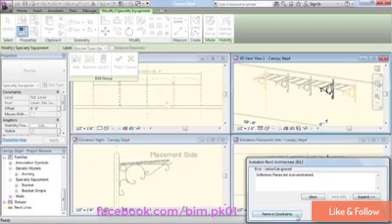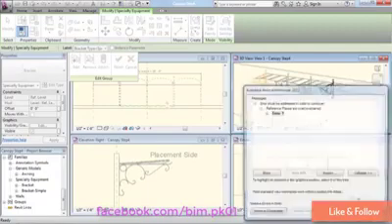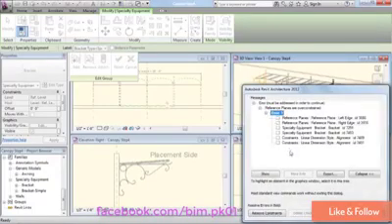Now, the constraints in particular is you'll notice that it's highlighting our 2 bookends. So somehow Revit is not happy with the constraints that we applied to the bookends, the locking of our family to the reference plane. And, you know, sometimes if you click expand, it tells you a little bit more information. And all it's really doing is confirming that the 2 reference planes are involved and the 2 specialty equipments and some dimensions that I can't really see in this view. So unfortunately, as I said, remove constraints is really the only way that we can continue.